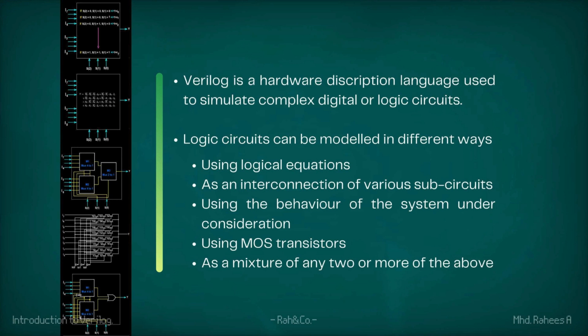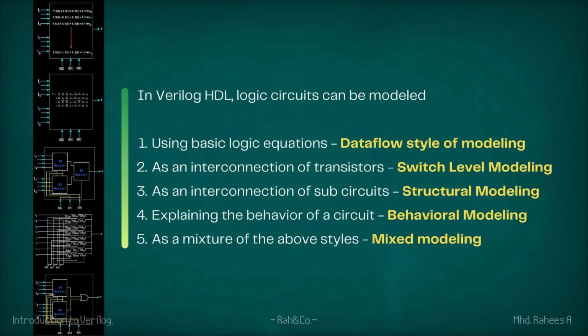Different types of modeling. Verilog is a hardware description language used to simulate complex digital or logic circuits. Logic circuits can be modeled in different ways: using logic equations, as an interconnection of various subcircuits, using the behavior of the system under consideration, using MOS transistors, or even as a mixture of any two or more of the above. If we model a circuit by using basic logic equations, then the style of modeling is called data flow modeling.